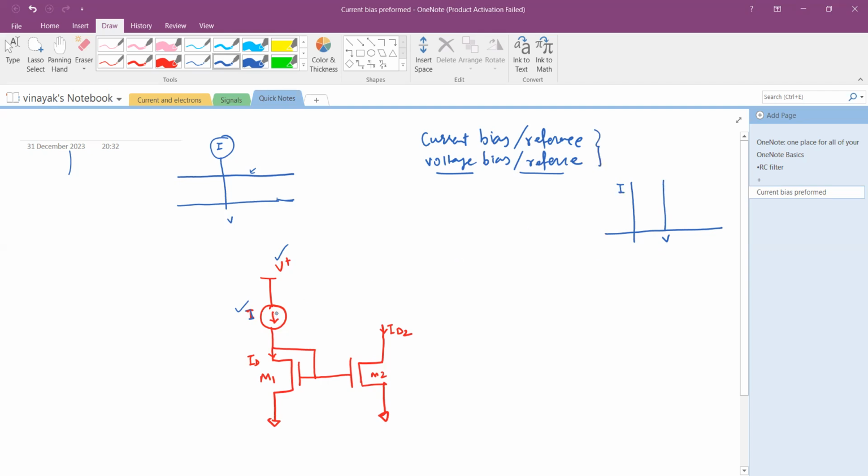So here in this circuit, there is an example. I would use, for example, V plus here, and I can use a simple resistor instead of this current source to generate the same current I, because the current that will flow is my I. And then I use the MOSFET, exactly as shown, to bias and do the rest of my circuit processing and signal processing.